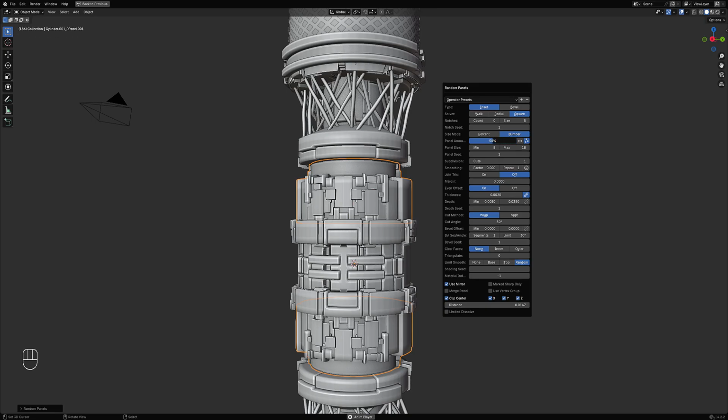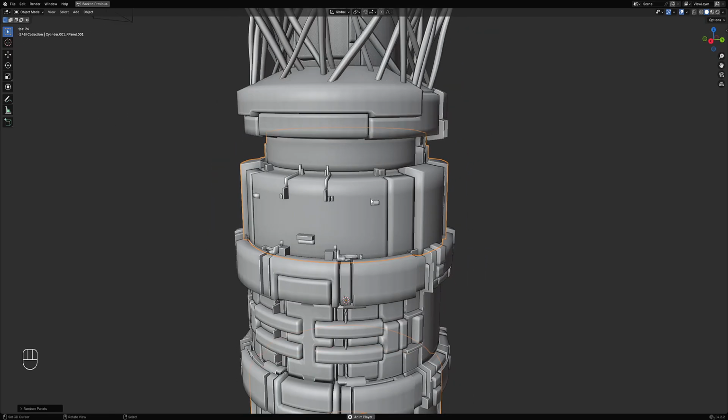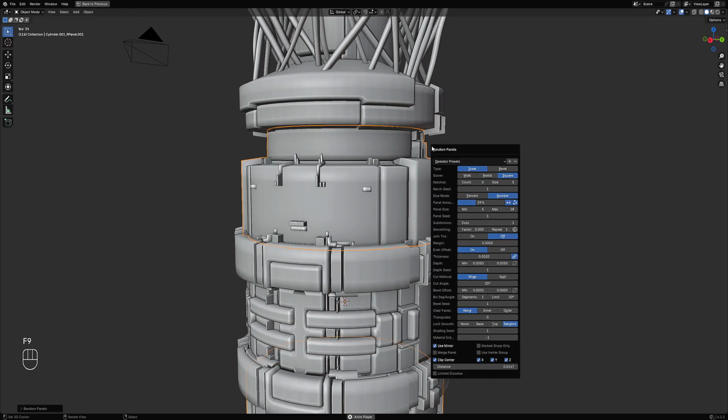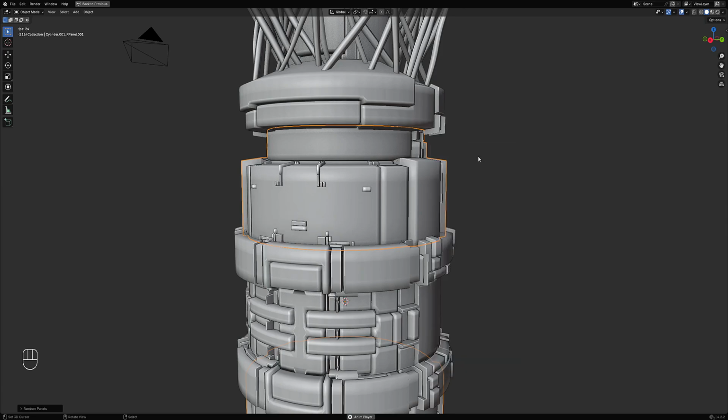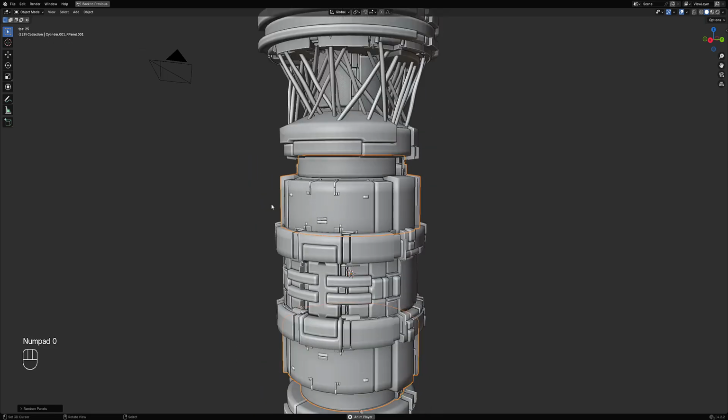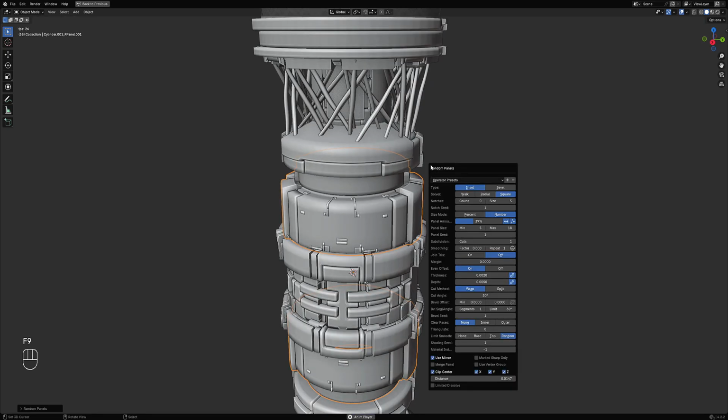Then we need to remove the objects. Make sure this is toggled on. So it removed the smaller islands first. We need to remove the bigger islands first and get us this geometry, or leave us the smaller panel islands for the tiny details. F9, and we're going to just use a constant value for the depth. Okay, 0.005. Okay, so we have that.